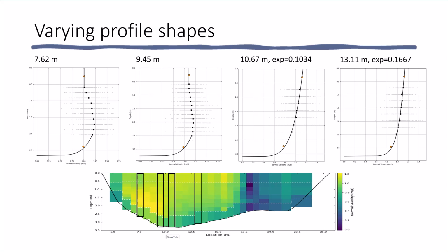The profiles nearest the channel banks have an influence from the bank shape and roughness, and those near mid-channel for a wide stream approach the more theoretical shape due to the diminished influence of the banks. The deviation from the 1/6 power curve varies by just over 2%.